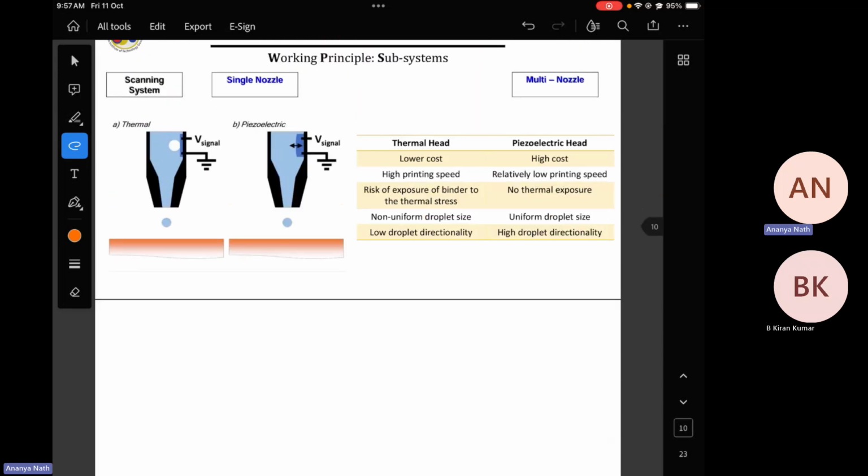Yes. So there is a piezoelectric material. By the application of external voltage, the piezoelectric material shrinks or expands. As you increase or decrease the externally applied voltage, that piezoelectric material can be shrunk or expanded. For example, if it is shrunk, then the drops will come. If it is expanded, the drops will not come. Then you control the voltage in such a way that the piezoelectric material will shrink and expand, and accordingly the droplet will come only when it is demanded.